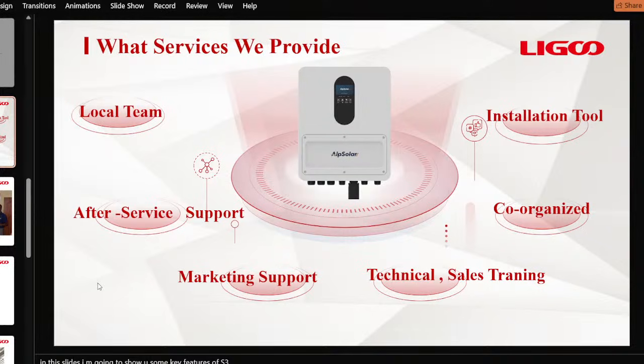Now you're talking about both AC and PV inputs can activate the lithium battery. This is another key feature whereby you have the BMS of your battery shutting down the battery. This inverter can wake it up by drawing more power from either the PV, it can start up, and also from the AC, you can also start up the battery without going on any other connection or wake up call. See, this is the wake up call from it.